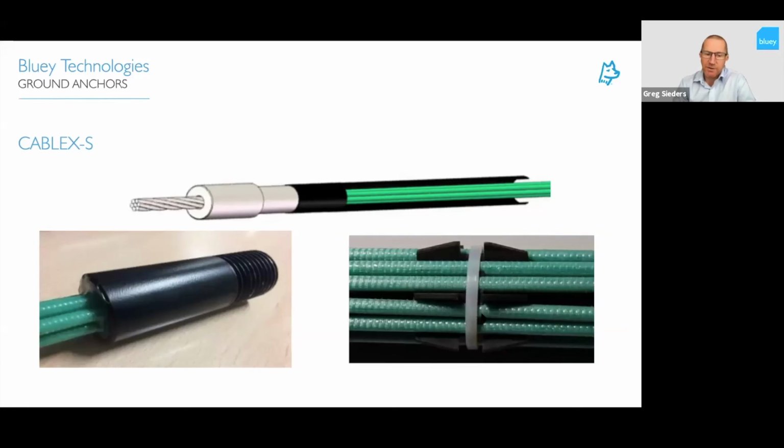And this is just showing you the makeup of those GRP bundles. This is a connection piece, which you see here, which then connects to a standard steel strand for doing your stressing. Makes life easier on site for stressing with a steel strand and locking them off. Then they just de-stress them, leave them in the ground, and then they can cut through later on with no issues.